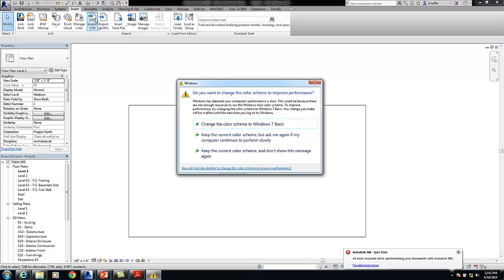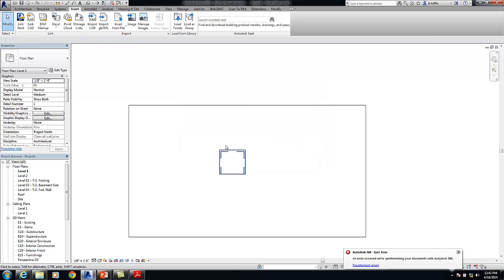A lot of different ways as far as the clear zones. It's a newer thing. Autodesk really hasn't addressed the clear zones and maintenance zones yet in their content style guide. It's something that the manufacturers are really starting to request. But there's no plot right now that I've found. You could put a visibility parameter on the family and clear them. Oh, definitely. Inside families, the statement was an answer to that as a workaround, is visibility parameters.